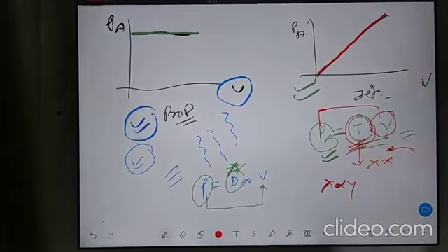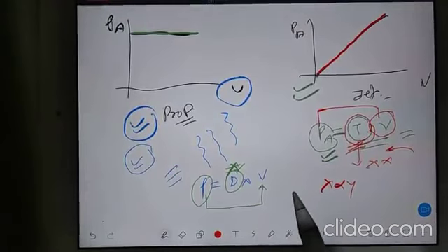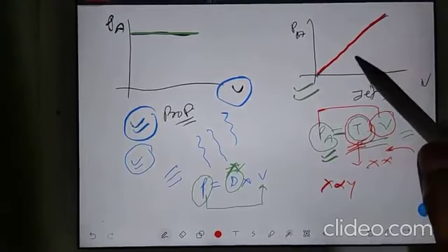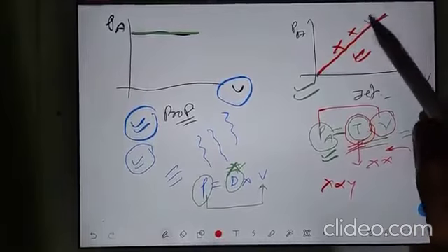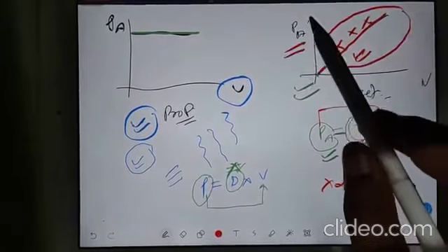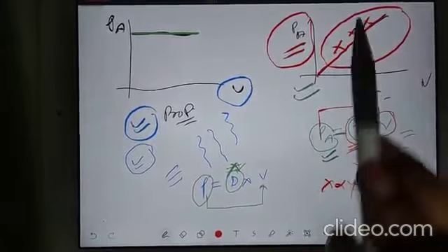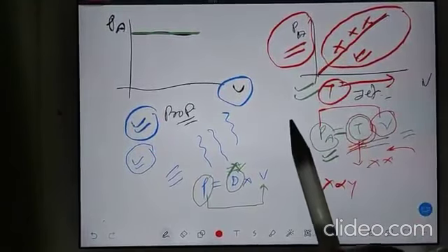Okay, now we'll go in detail so that you can get some more idea. If you think in this way, power available is definitely changing linearly with forward speed, and because it is changing, that's why we don't consider power available for the jet engine for the reference purpose. That's why we consider thrust available for the jet engine.